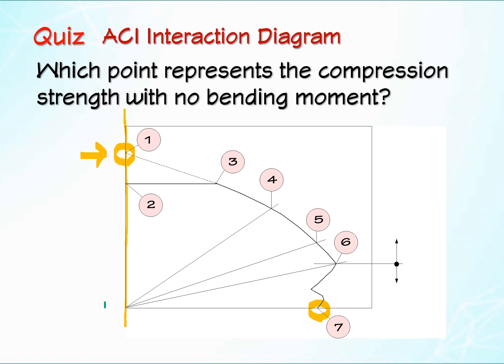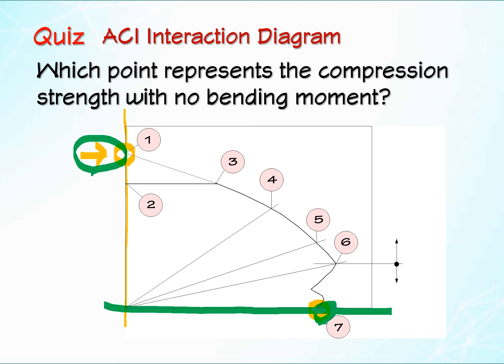And along this line, there is no axial force or there is no axial stress effect. Okay, this is column action, compressive failure, and this is beam action or tension control, tensile stress failure or yielding will occur in steel. And again, this was balanced condition.